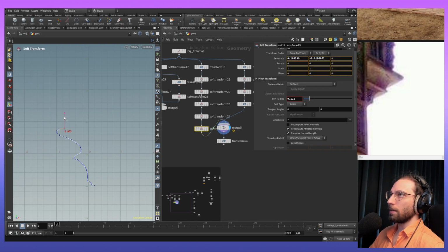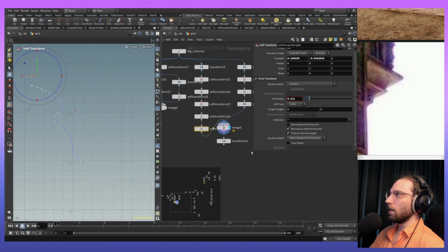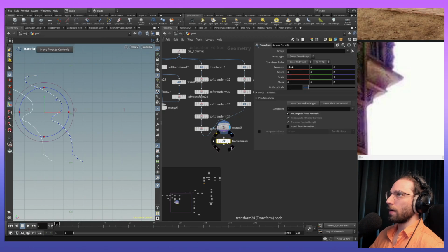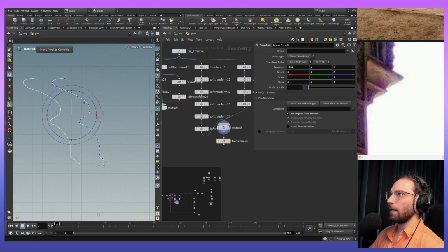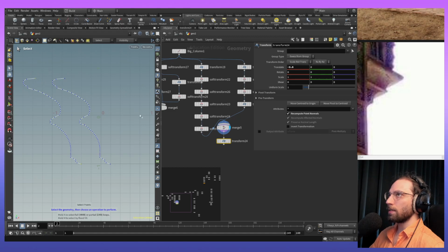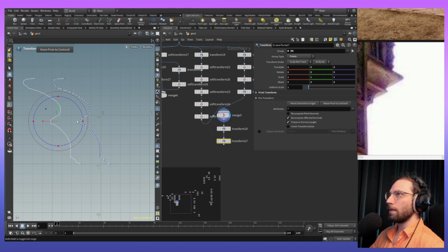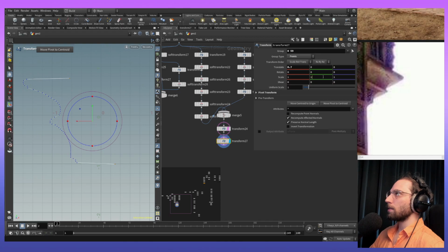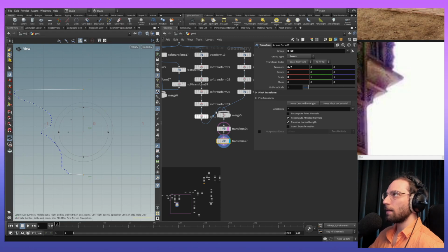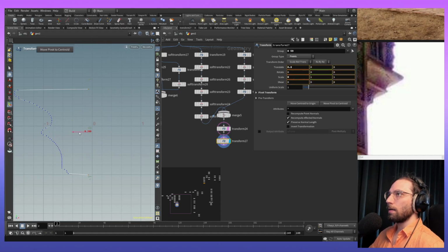What is the last thing we've done here? This thing here. Okay, it's not as pointy as the stuff we've done here, but for now we will go with it. We have merged and we will transform it away, and then again we will pick those 2 points and we will transform again, but the normal transform this time. We will reference the one behind it only, view the last transform, and then we will bring both of them in the scale to 0 in one of the axes, so they are at the same length, and then we will take them to 0, 0, 0.